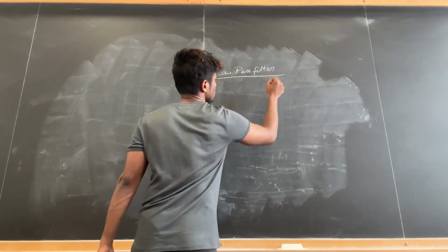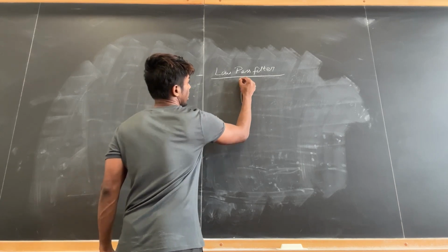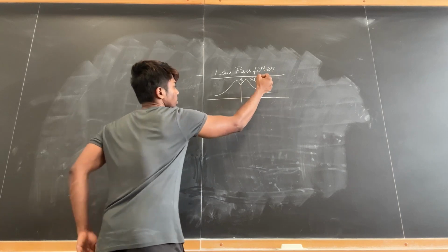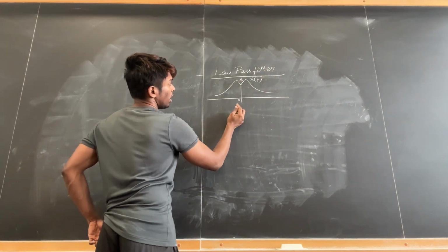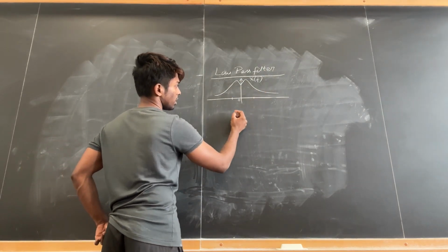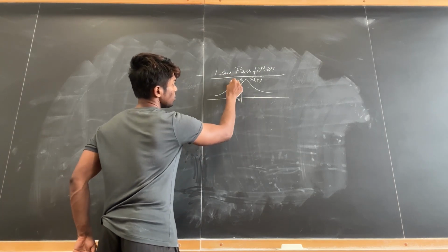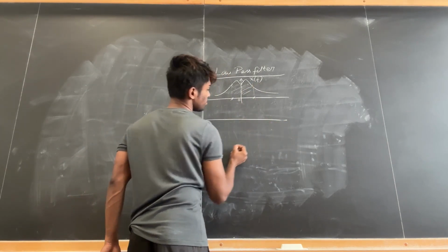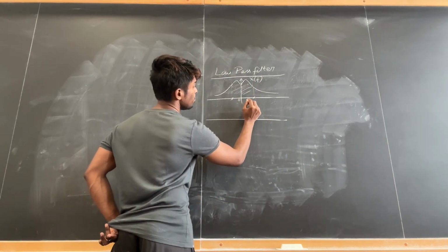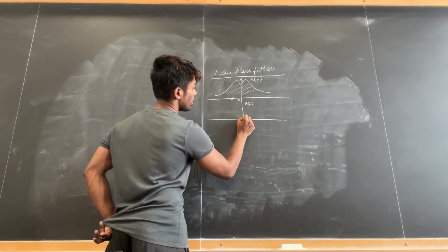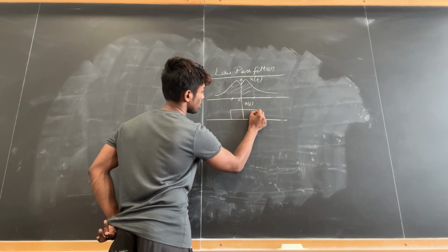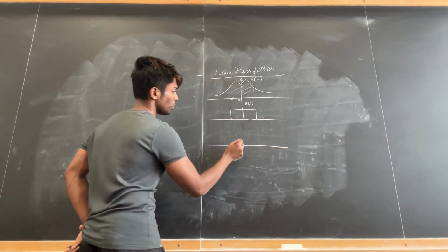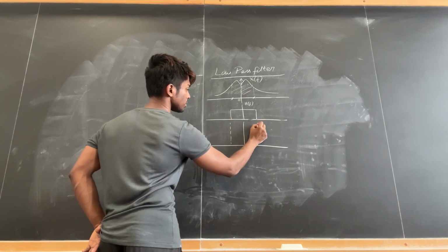So an input with a response as X(f) has a frequency response something like this. This is X(f). This frequency response has some lower frequency cutoff, and after that cutoff it can only pass until those frequencies. So the system that will pass only those frequencies shall have a frequency response H(f) as a rectangular function, something like this. Multiplying these two, we shall get an output with only the lower frequency components.